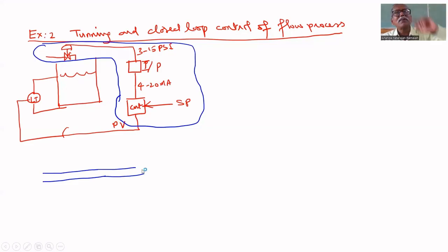Because what is the frequency of power supply? 50 hertz. That's why it should rotate at a constant speed. Then only you will get 50 hertz. Otherwise, you won't get 50 hertz. So, irrespective of load, it should rotate at the same speed. That's why a controller is required. Suppose the generator is run by diesel, it will adjust the diesel flow rate.